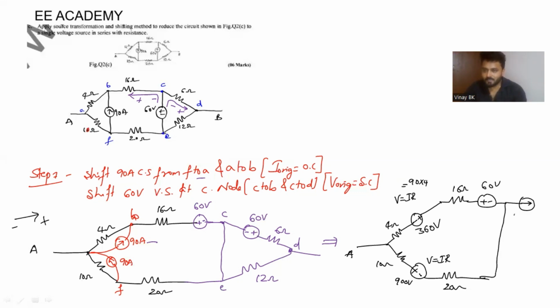See here, this I is given by V divided by R, whereas V is 60, R is 6, you can get 10 ampere of current. 10 ampere of current that flows from C to D. Again, the resistor will be parallel, that is 6 ohm is parallel to 12 ohm. This is B. I hope you're getting this.